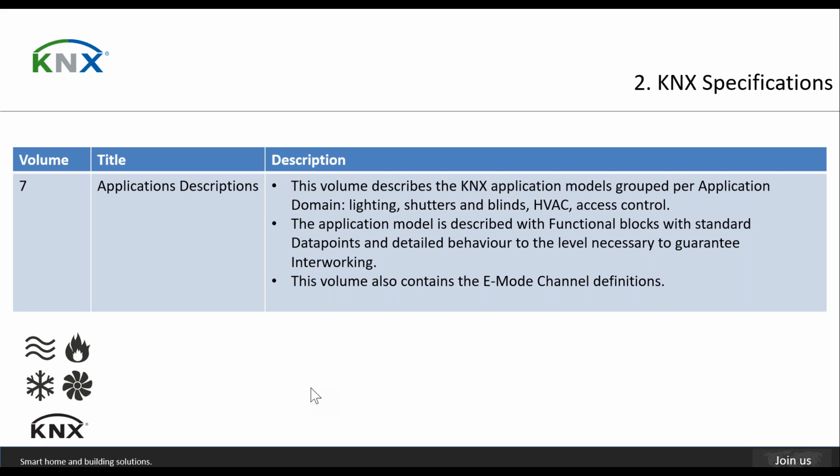what's the purpose of this? For instance, if we have a thermostat controller from one manufacturer, and we have a thermostat controller from another manufacturer, and a HVAC controller, like could be a fan coil, they might have interoperability in terms of the data they share, but they may use different data point types.